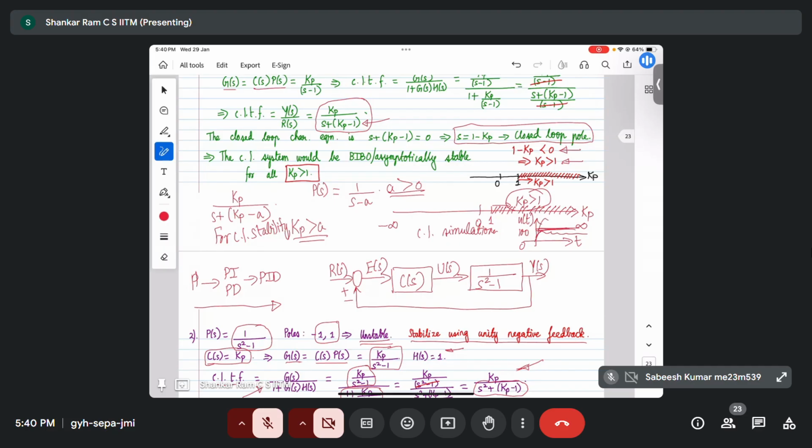But if during simulation your actual control input, with this Kt being 1 lakh, goes beyond the capacity, you need to change the actuator, right? So there is no other way, right? So all those considerations will come later, like whether you will have an actuator to realize the control action that you are seeking. That is the next step. I hope that becomes clear, right?